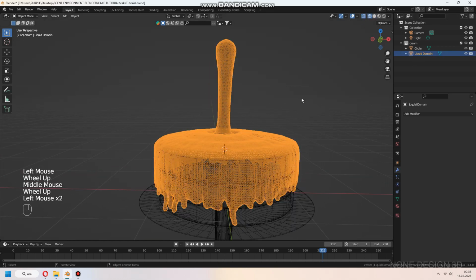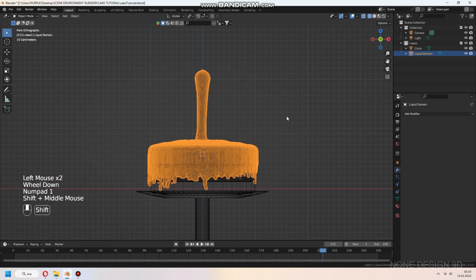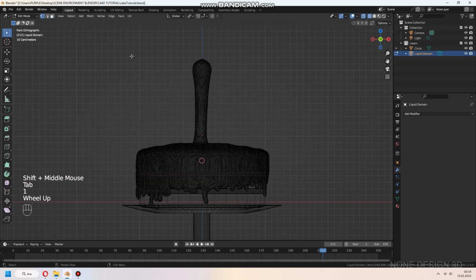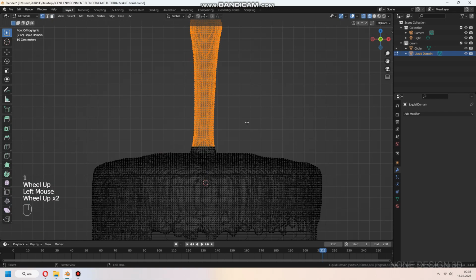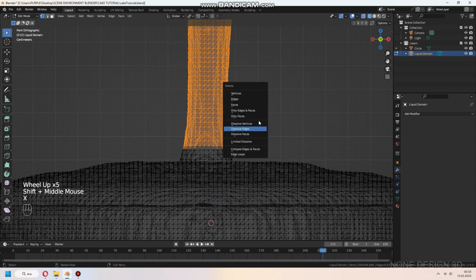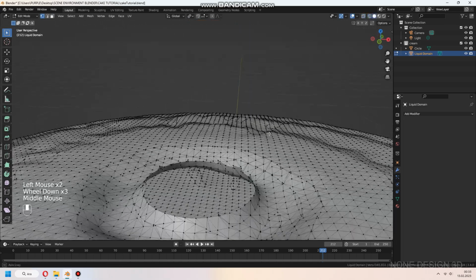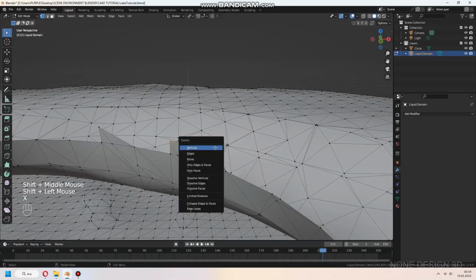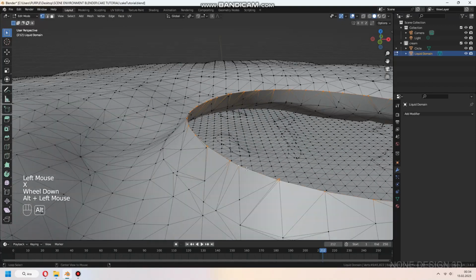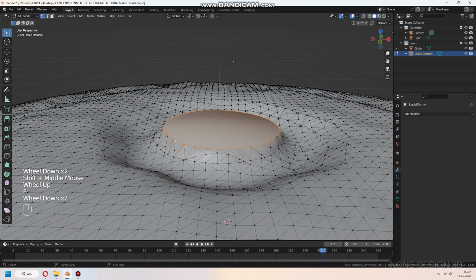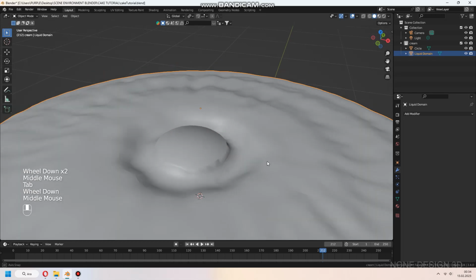For a straight view, let's cut this part. In viewport X-ray, select the mesh and go to edit mode, choose vertices and delete them with X. Select all circle vertices and F to fill.